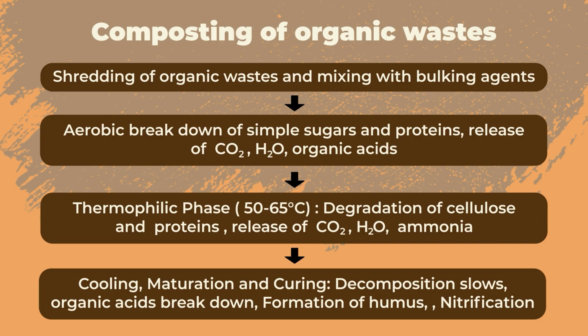Then the microbes will decompose the organic material present in the waste. In the aerobic breakdown of simple sugars and proteins, carbon dioxide, water and organic acids are released. In the next step, there will be heat generation, the thermophilic phase, where the temperature will be around 50 to 65 degrees centigrade, and the microbes degrade the cellulose and the proteins and release carbon dioxide, water and ammonia.